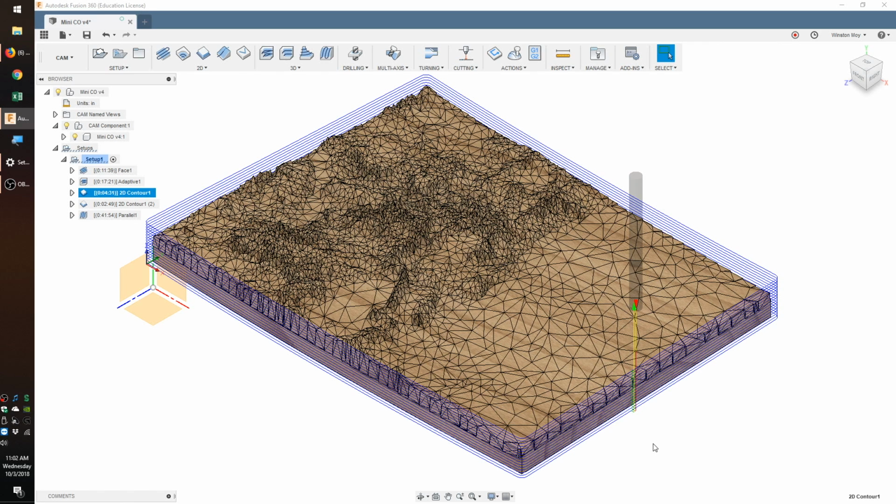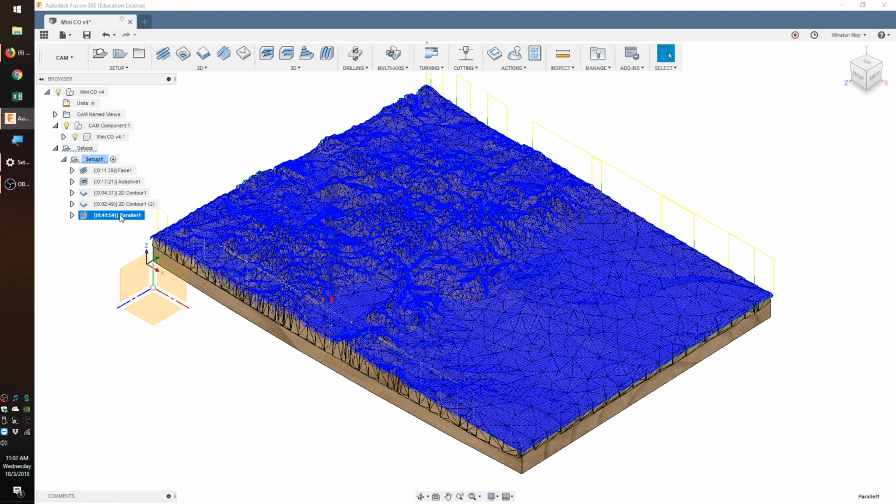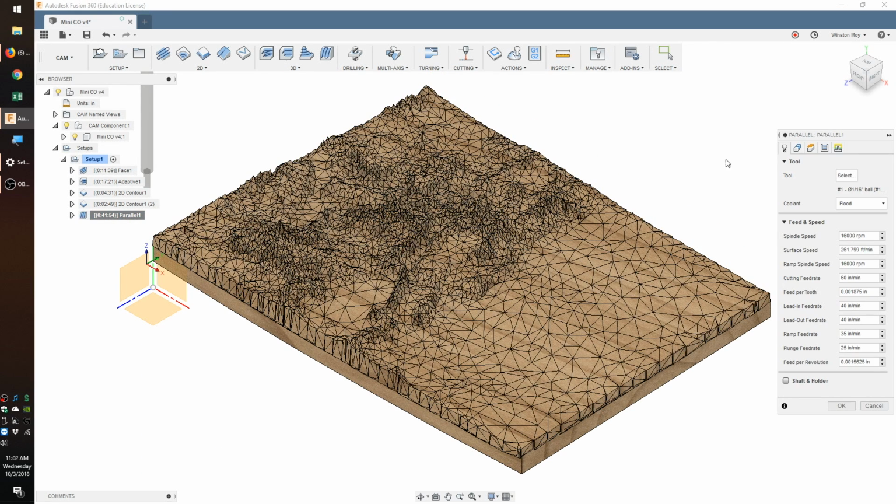All of the toolpaths up to this point used an 1/8 inch end mill for convenience. Sure, using a 1/4 inch cutter would have been faster for facing, but it saved me from having to do a tool change. To wrap everything up, I used a parallel toolpath to smooth out all those delicious 3D contours.